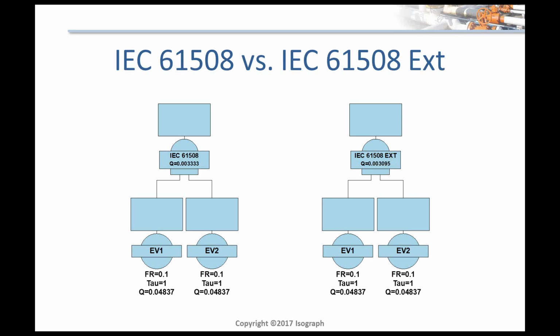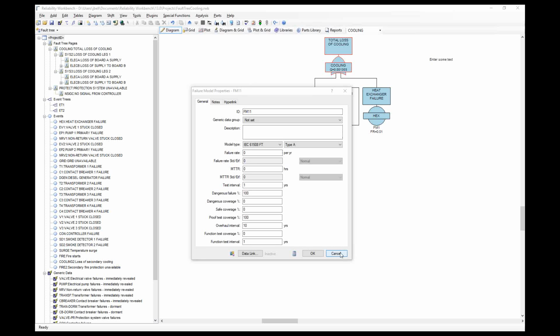There were some users who didn't like to use the 61508 model or the averaging, because they're saying, we're getting pessimistic results. We know that our actual SIL level, our SIL verification is actually better than what the program is giving us, and even what the IEC standard will give, because again, it uses a lambda t over 2 approximation when it could be using something a little more accurate. So that's what we've added in, and let me just show you where that is in the software.